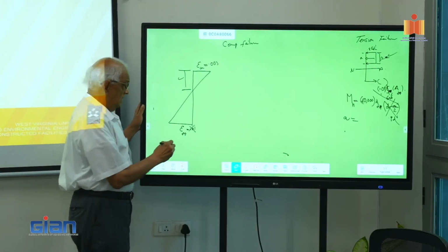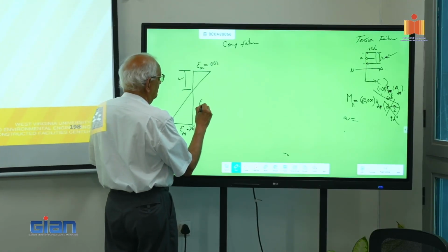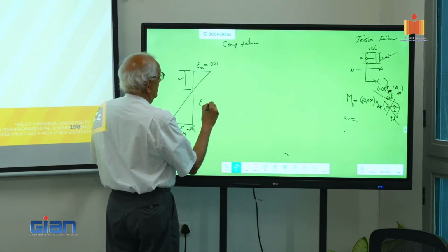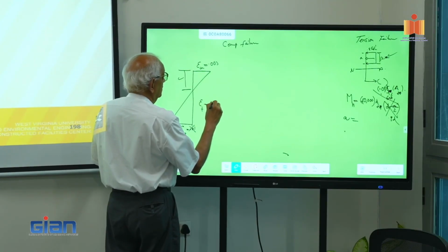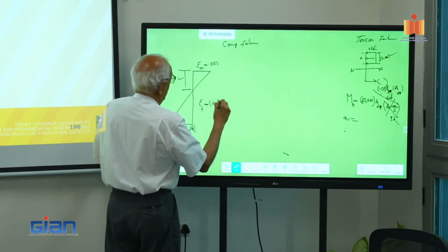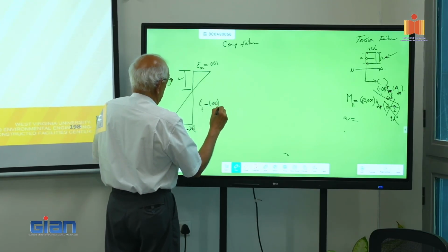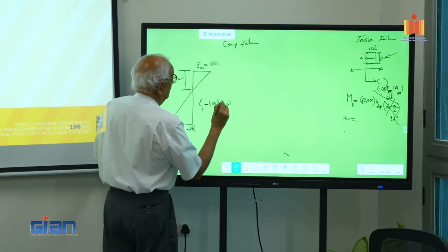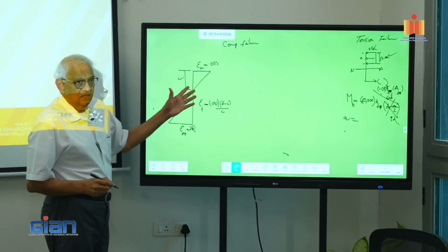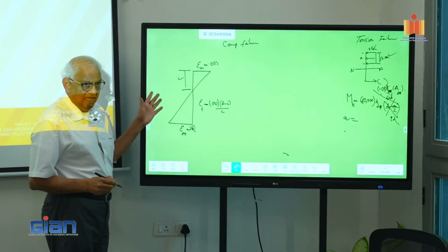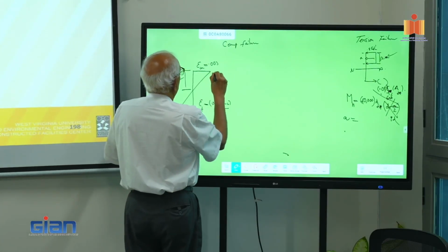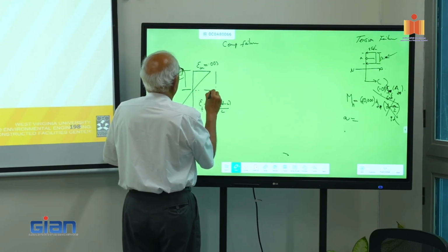So this is no longer that. The strain value in tension is going to be epsilon cu, which is 0.003, right? Multiply that with (d minus c) by c, right? Then that is the compatibility. This is what we call strain compatibility. So then this is in an approximate sense.